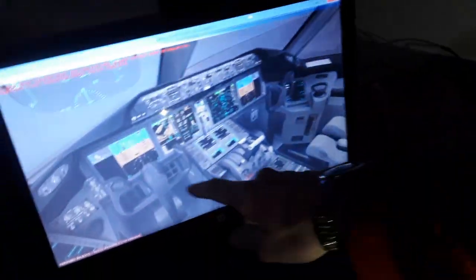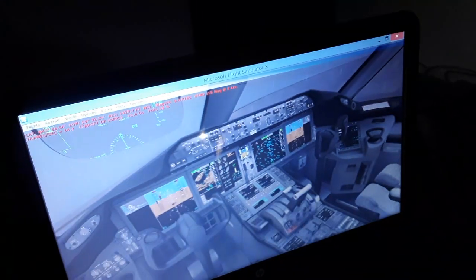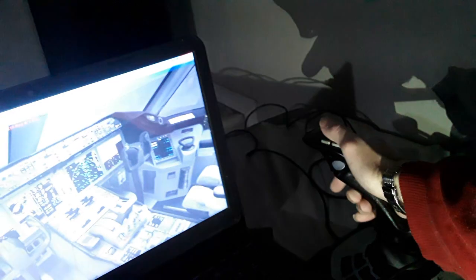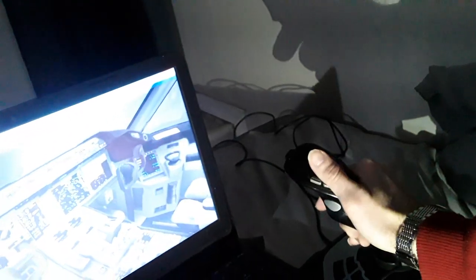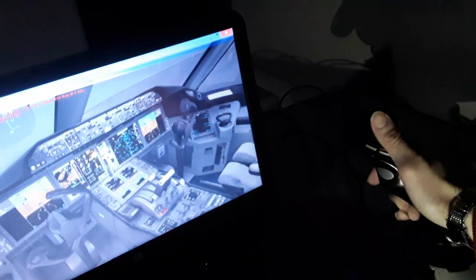So you can see here we have the auto trim function. We also have the manual trim in the Boeing aircraft, the manual trim switch, or in the Airbus we have the trim wheel. We can input the trim wheel if we need. So I will show you here what I mean. You can see in the Airbus we have climb 30 degrees or 1.5G, descend minus 15 degrees, so minus half G, and making left and right turns 67 degrees at maximum side stick deflection on 2.8G.